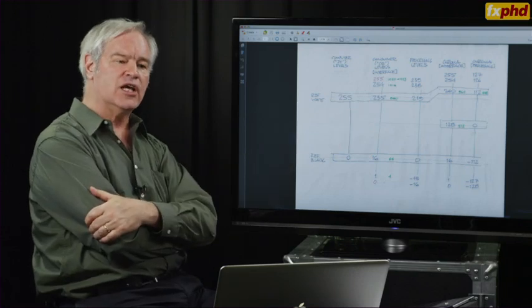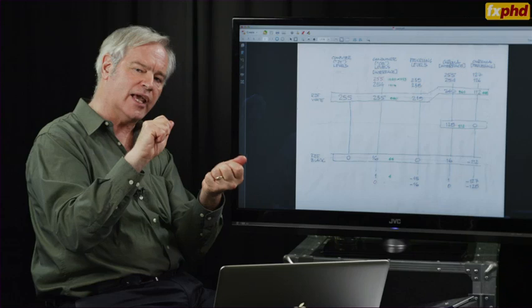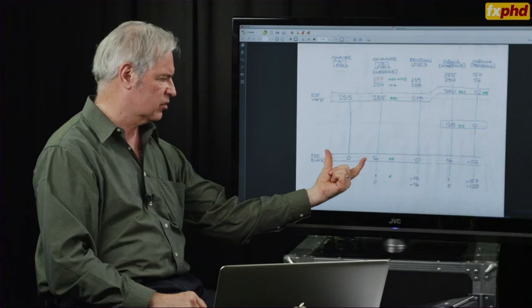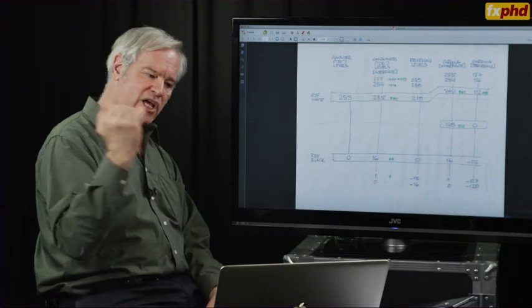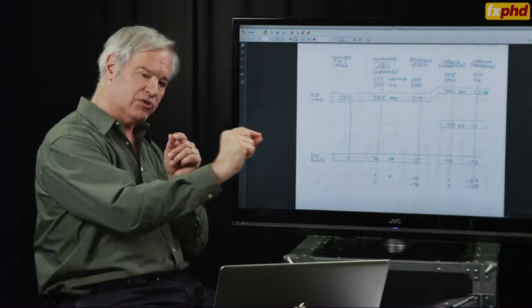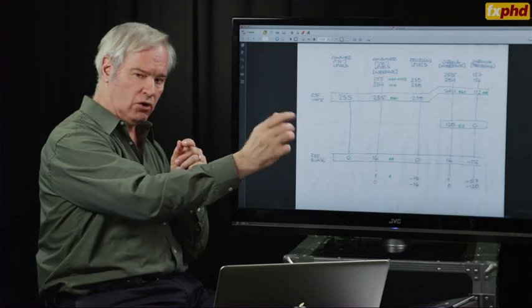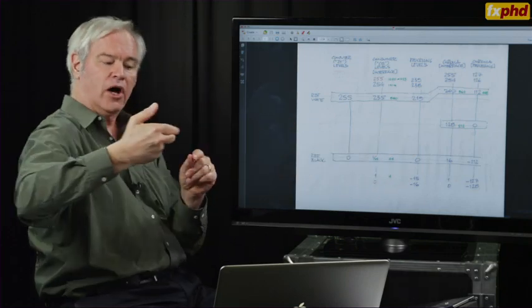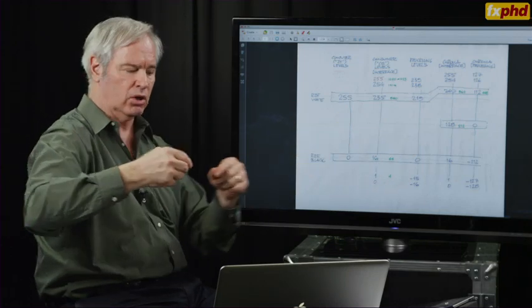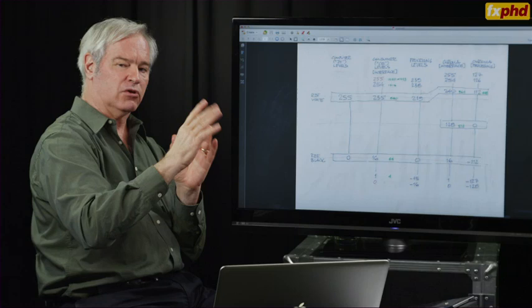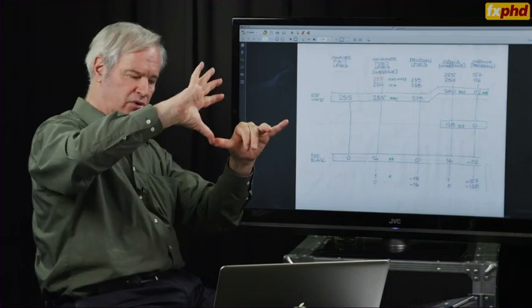And across an HDMI interface, you basically have 2 choices. You can use either one of those coding systems. And there's a mechanism for the HDMI channel to signal to the receiver which one it's using, and also to query the downstream receiver on which variations are available. HDMI also queries the receiver on what pixel counts are available, the number of rows and number of columns.